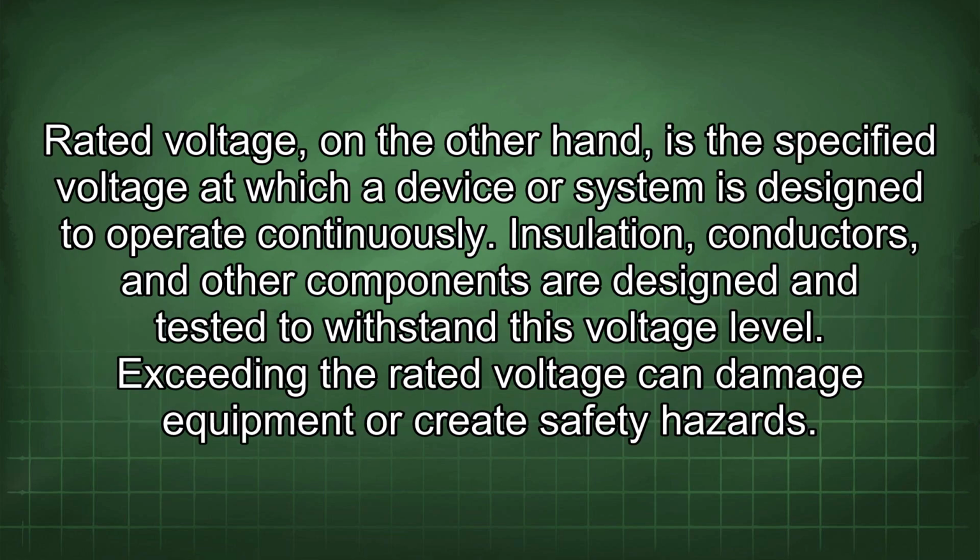Rated voltage, on the other hand, is the specified voltage at which a device or system is designed to operate continuously. Insulation, conductors, and other components are designed and tested to withstand this voltage level. Exceeding the rated voltage can damage equipment or create safety hazards.